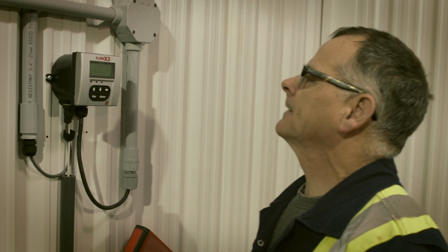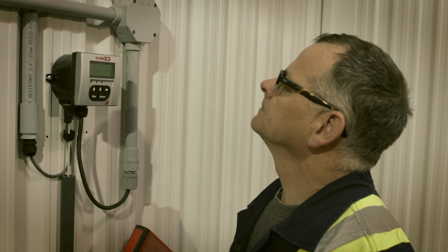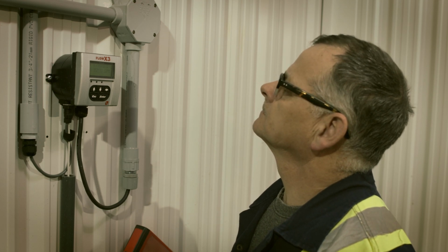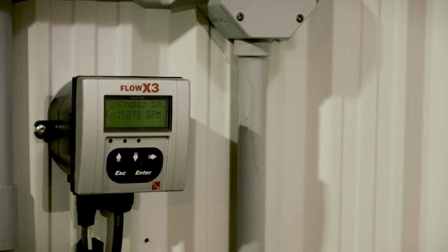They can either read the flow data directly from the register on the flow meter, or the flow data can be recorded remotely through a SCADA system. When monitoring flow rates from the flow meter, there is either a register mounted directly on the meter or there is a wall-mounted display. Most flow meters will display an instantaneous reading and a totalizer reading.